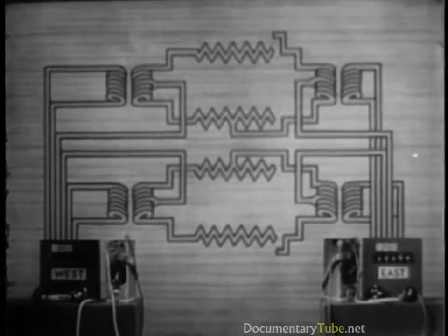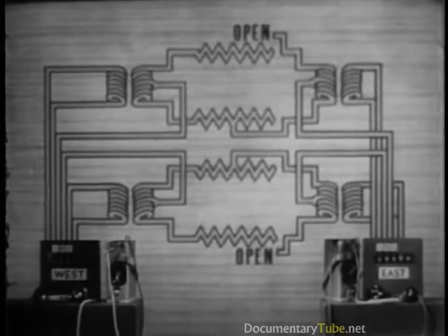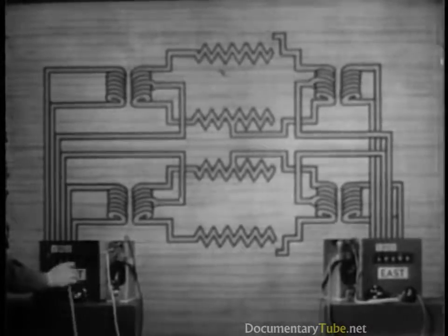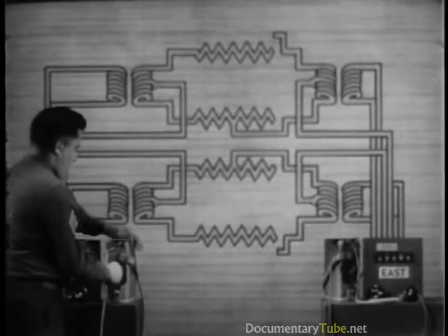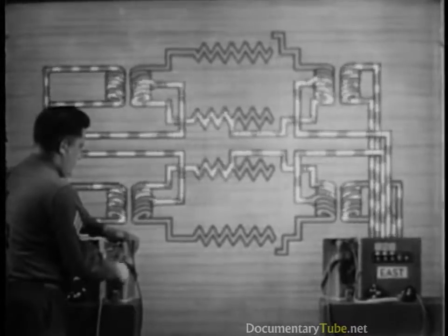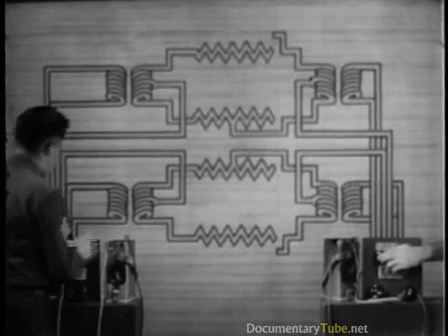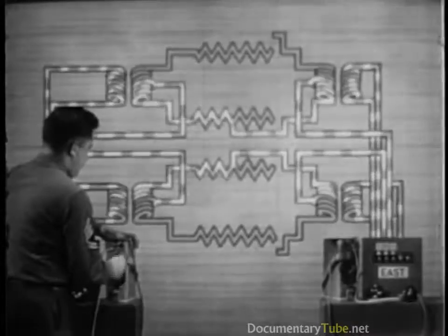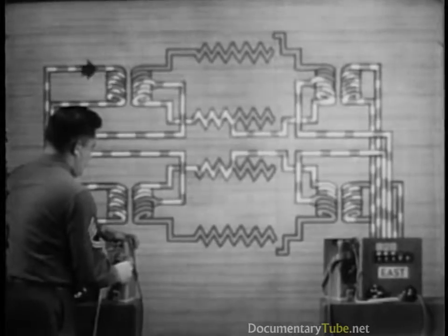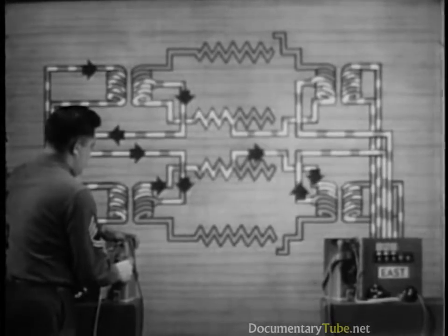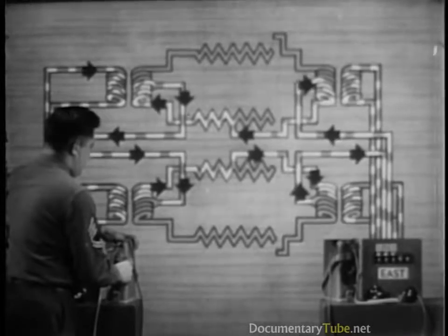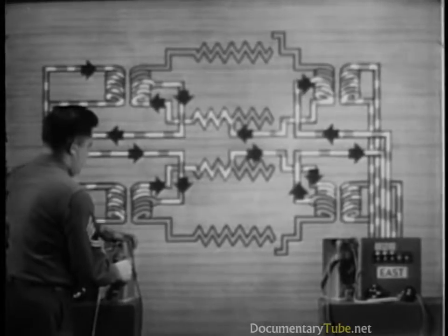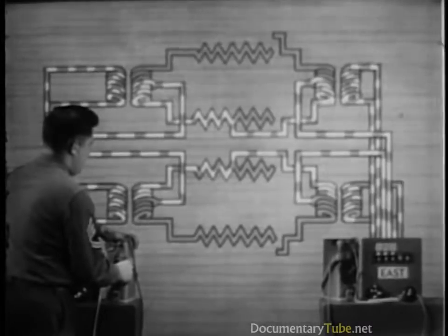What happens if both side circuits are open? This one's tricky. Now, both sets of repeating coils are unbalanced. Ringing on either side circuit, we find that current flows through every possible drop in the phantom group. The jack we ring on is, in effect, connected in series to the other 5 drops. Either side circuit then interferes with both the phantom and the other side circuit.